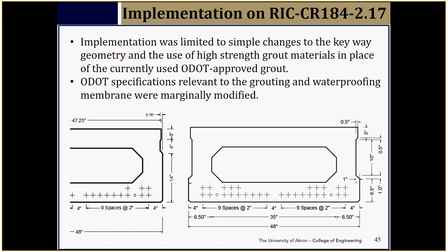So the answer to Tim's question: are you then saying that the combination of all those movements is in fact destroying the membrane as a possibility? Yes, the possibility is that the fundamental behavior is the beams will behave like single units the moment the joint cracks. That's what happens. So if we have a deeper keyway joint, we are trying to transfer the load over not just one beam, but maybe two or three adjacent beams, because the joint is still intact and it's able to transfer the load between beams.